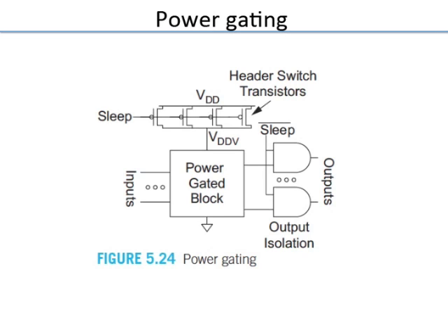If you make the assumption that everyone switches at the same time, you will end up with a current which is so large that putting a power gate of that size will not be feasible. I is so large that I times R means R has to be very small, size has to be very big.